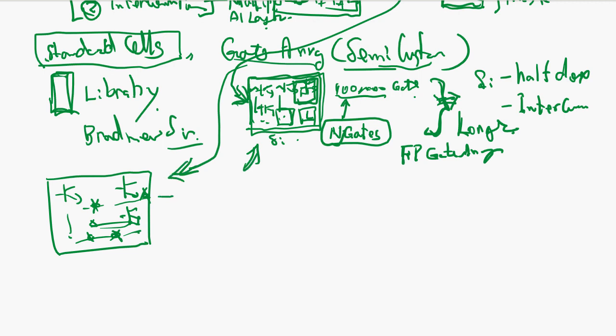So that's called a field programmable gate array. Okay, and nowadays this has become more popular for time saving, and the cost performance is better, because with the gate array you still need to generate an interconnection mask and go through the wafer process.